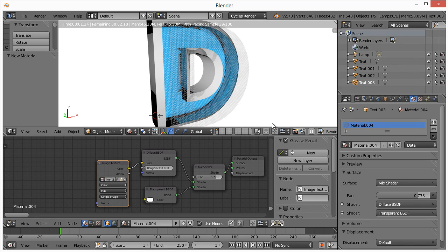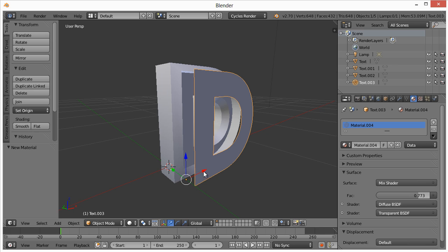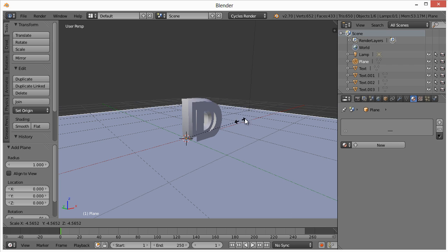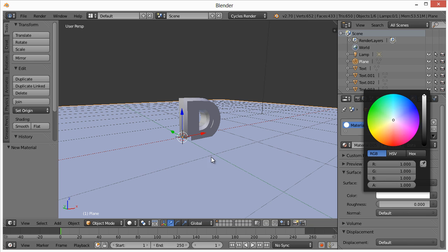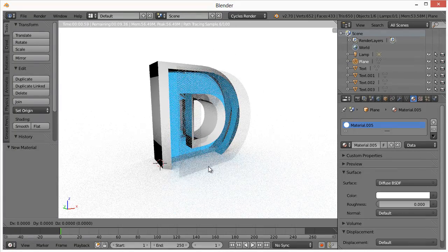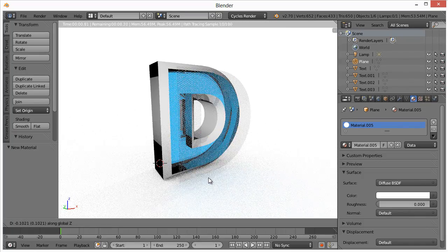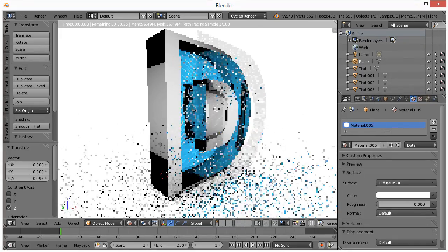All right, so now I'm going to right click on this middle section and just hit Join Area Down. And then finally, we'll go back real quick, and our last step will be to Shift A to add a plane, hit S and just drag your mouse up quite a bit. We'll give that material, we'll make it 100% white, switch back to rendered, hit G and then Z, and move your mouse down so that these are sitting just right on it, the letters in this interesting design basically.